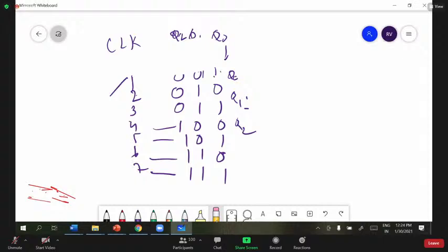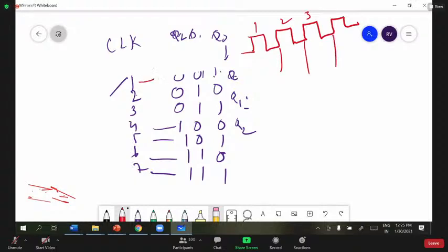So to draw the timing diagram for this, you have to take the clock signal first. So a proper clock signal we take like this, and mention up to here. It is 1 we consider. This is the second clock pulse, this is the second, a third. You can consider this. And suppose I am taking this, but it functions only during the negative going edge, no? So I am concentrating only here. Extend its operation up to 7 clock pulses.